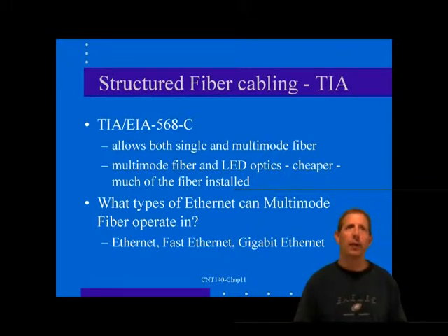Initially, the network technologies that were to be supported required modest performance parameters to support networks with 10 to 20 megahertz bandwidth. However, the speed target has moved rapidly upward until we find the standards now supporting link testing limits of 100 megahertz to 250 and even 650 megahertz. Now, as the cabling standards have moved forward, the ability to place these higher speed networks on the cable plant has advanced as well. Fiber optic cabling is an important part of cabling technology and adds to the wealth of options available to the network technologist.